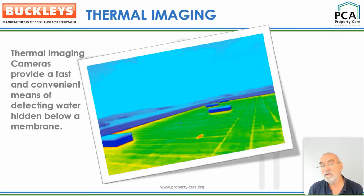Infrared cameras are a convenient method of detecting water hidden beneath a membrane. Water has a very high specific heat capacity, thus it can be readily detected by a temperature difference between a wet area and a dry area. This is particularly effective early on sunny mornings when the dry areas of a deck will warm much more quickly than any that are saturated. And at night, of course, when the damp areas will take longer to cool. This method proves that water ingress has occurred. It typically does not provide specific guidance in the location of the leak that allowed it.